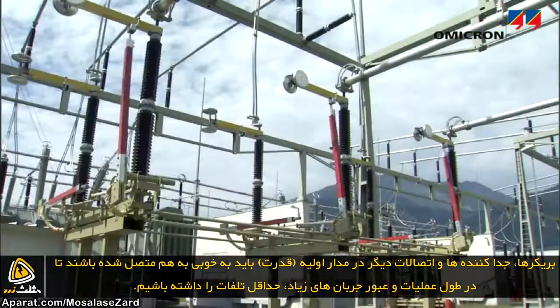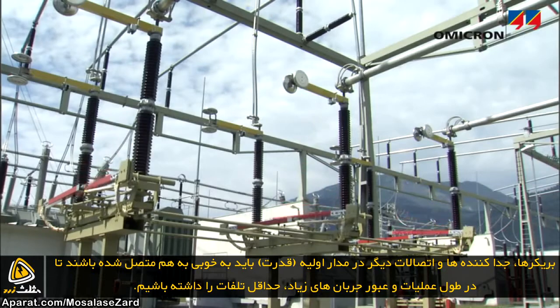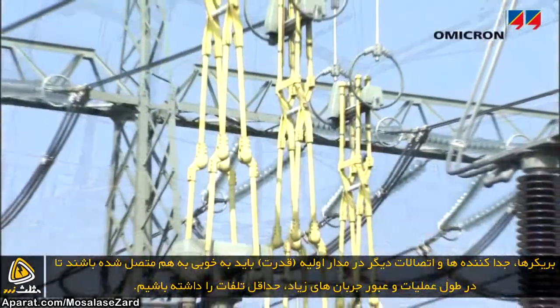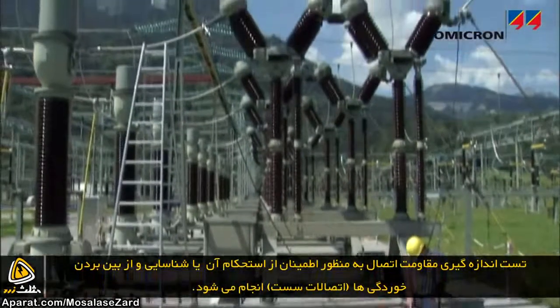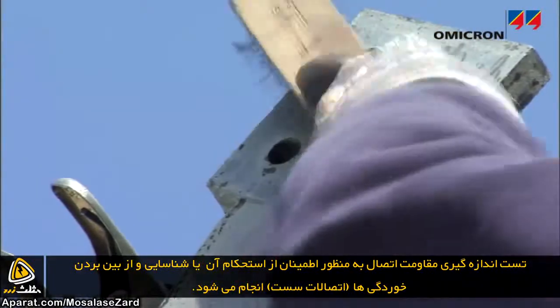Circuit breakers, disconnectors, and other connections in the primary circuit must have good contacts in order to allow operational currents to flow with minimal losses. Contact resistance measurements are performed to ensure tight connections or to identify and eliminate corrosion.